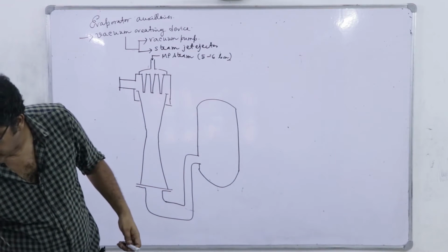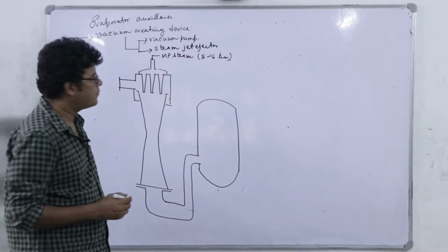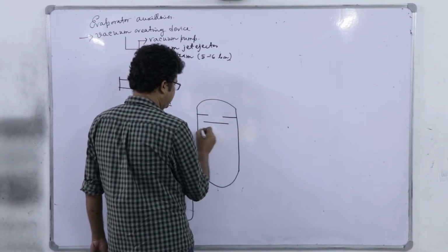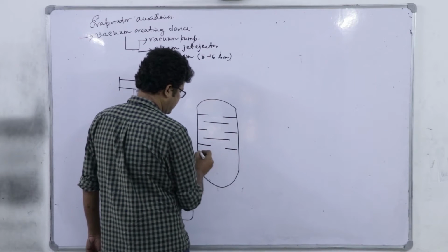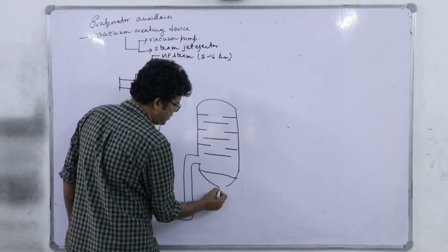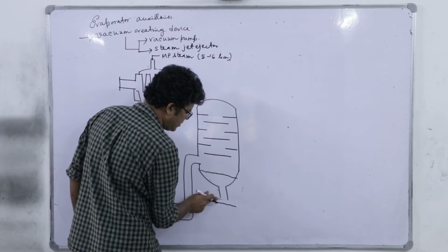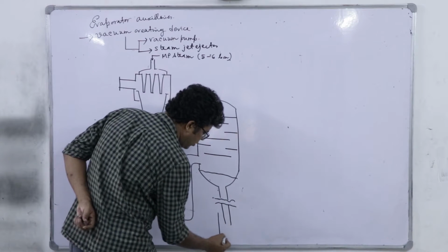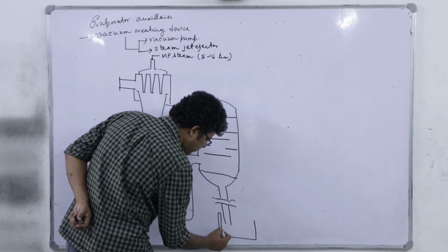This direct contact condenser has contacting plates, deflector or contact baffles, whatever you can say, and from here the condensate comes out through a long tube which is called the barometric leg, delivering the liquid into an open container which is of concrete structure. It's called the hot well.